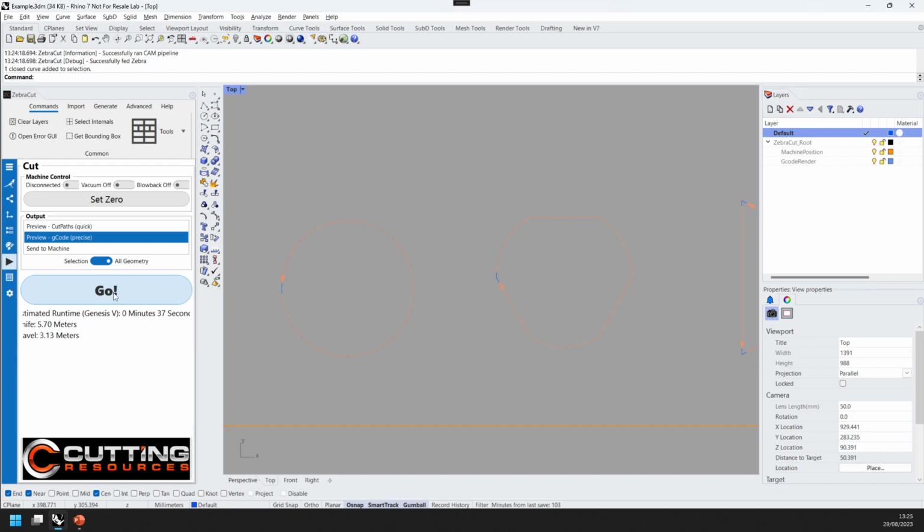And you'll need to find the right settings for your geometry and your tool. So there we go. If we put that down to 20 degrees, you'll see we actually do the correct undercutting on all of the corners of that shape. Similarly on this shape here and on these two nested squares.